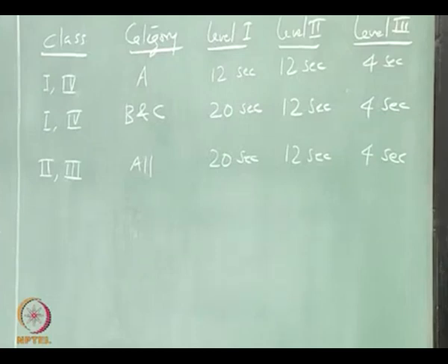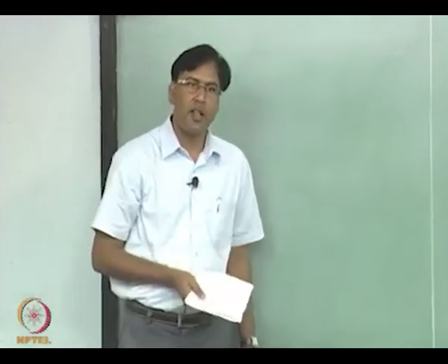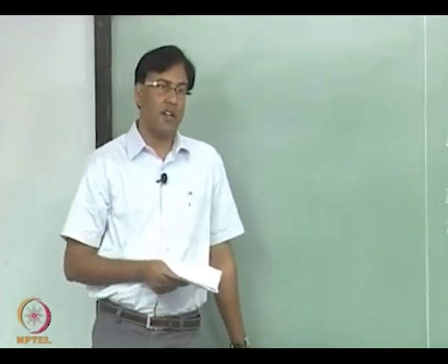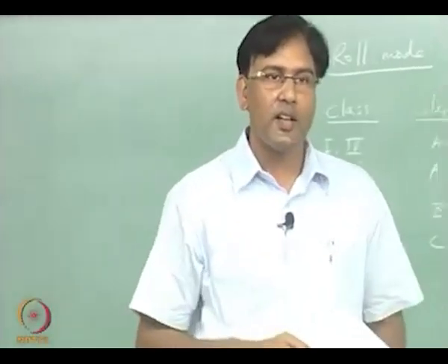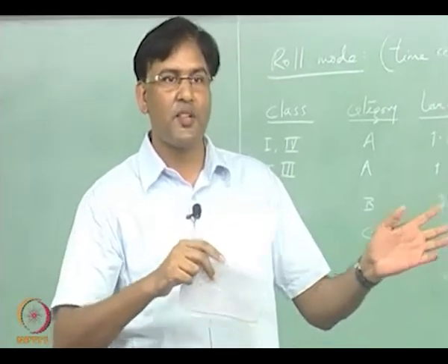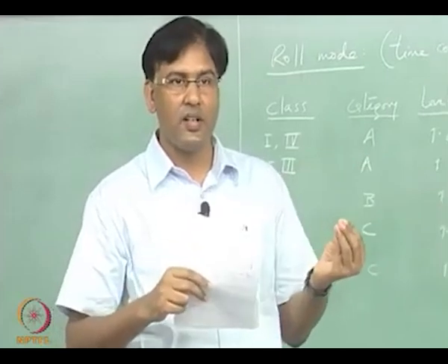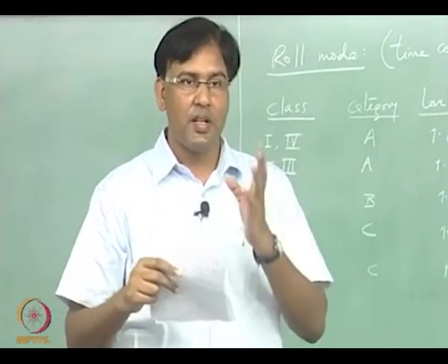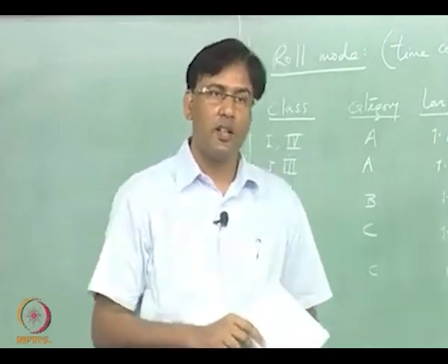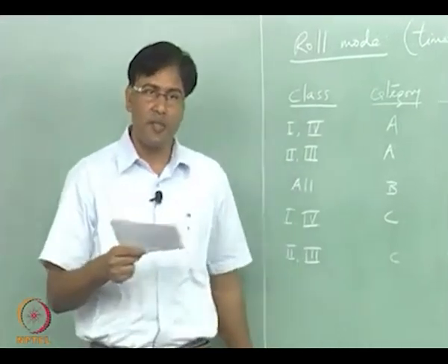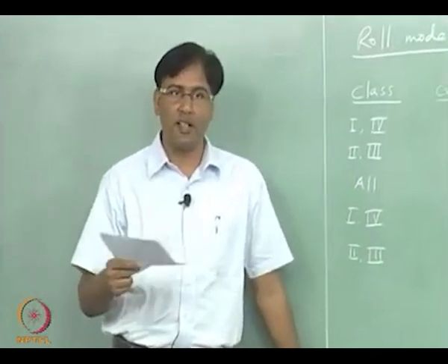talked about much. Remember, we said that we are getting quartic equations in lambda, right, and the coefficients are going to be functions of the parameters of the aircraft. And to solve that equation is a really difficult thing. Now, even if I have to solve for the numerical values, let us say the coefficients are given some numbers, right, even then finding out any information from there may be difficult, is not it.